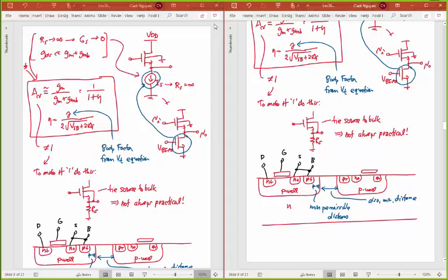Whereas if you put all of your transistors into one well, you can get them a lot closer. And so all of that, as opposed to this situation, where I have one transistor here, and I can put another transistor right here, very close to one another, without having to have that large gap between them. And I'm able to do that because all of them share the same well, which I tie to ground.